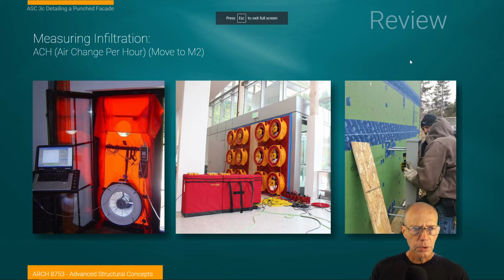One last thing. This is just some telling issues about where we're going with building performance. So on the very far right here, we have that siding system with the weather-resistant barrier, the green, already applied. You can see each one of the seams is well taped. So we have probably a center tape and then two additional tapes alongside of it to create a really strong seal between those two. We have any openings marked and then taped over.